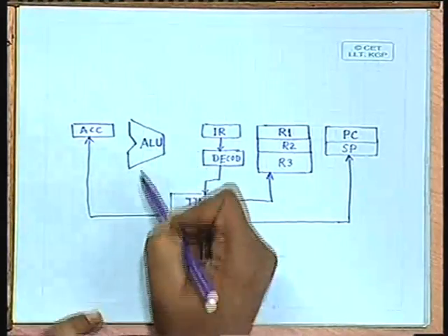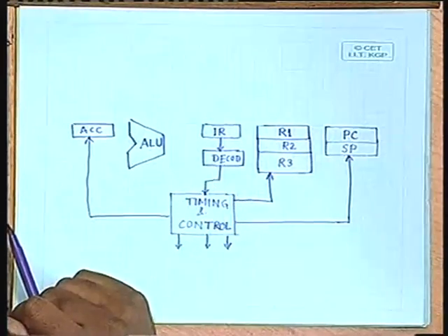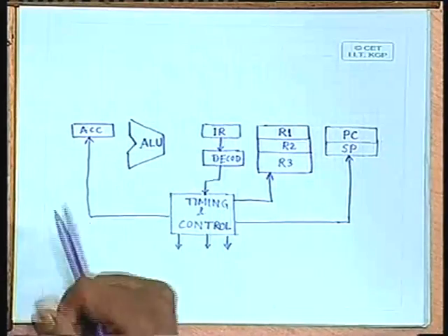Now, in many cases you have jump instructions. With a jump instruction, you decide whether to take a jump to some other instruction or whether to call a subroutine. This decision depends upon the result of computation. Say, for example, we give an instruction like jump with carry. After doing some arithmetic or logical operation, if a carry is generated, in that case the next instruction to be executed is taken from some function or from some other location in the same program. It is not the immediate next instruction which comes after the jump.